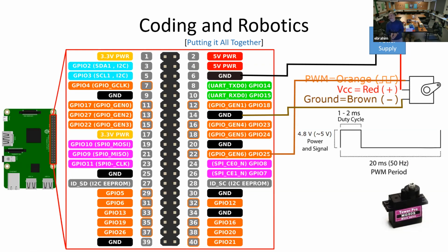So to be safe, you must understand all the interfaces and accordingly connect the device. From there, we saw that's why we need the power supply. So you can see how the design is coming. We've got a power supply at the top. And then the servo motor needs to have a ground, and we can connect the ground signal to the Raspberry Pi. We've connected there to pin 14. And also, what we need to do is the pulse modulation. We're going to use pin 22 of the Raspberry Pi connector and connect that to the pulse modulation signal.